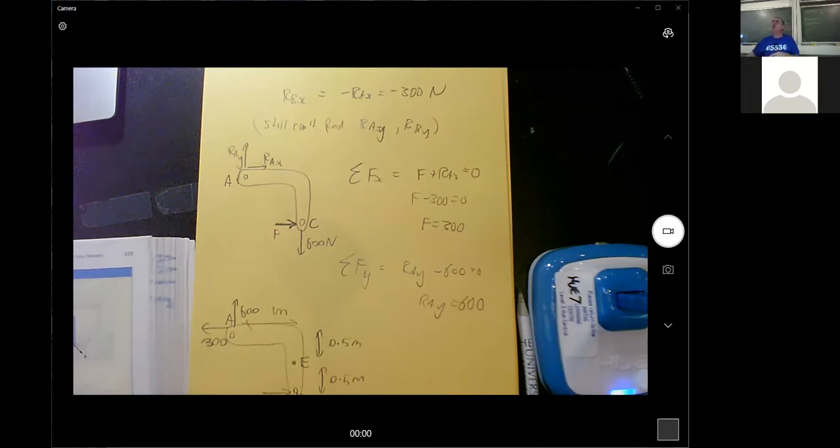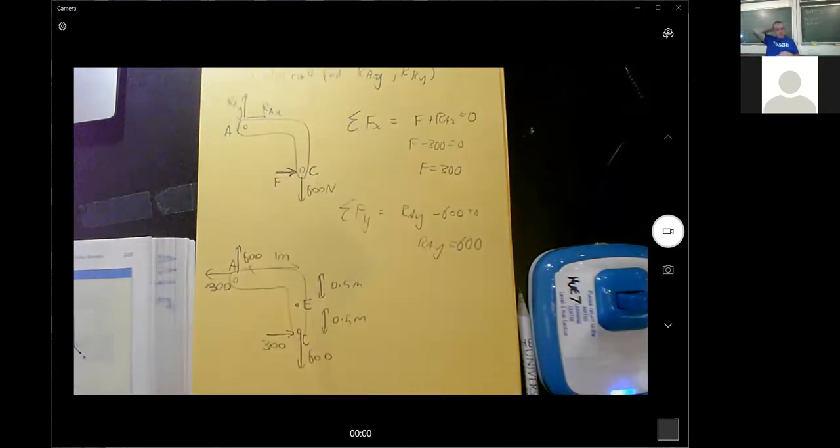Nope, it is 600. I was right. There are just extra moments floating around. I think there's a moment in this member, this corner, caused by this thing pulling as well. So, okay.